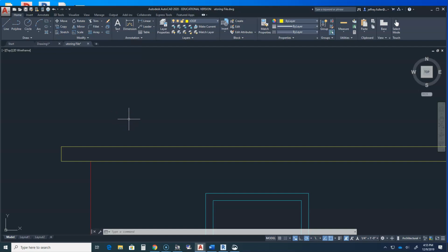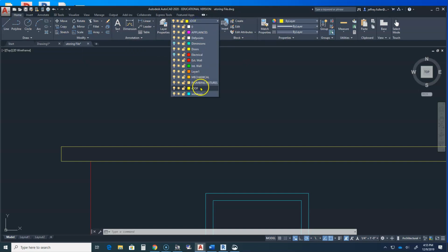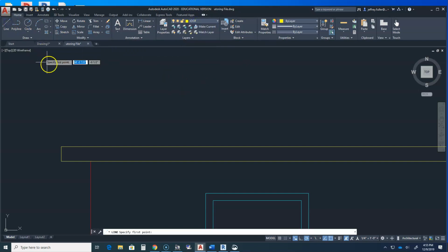over run. To establish this, we draw a couple of construction lines using the standard line tool. Go ahead and set your active layer to roof. Type line in dynamic input or select the line tool from the draw panel. Set the start point of the line at the top left corner of the fascia. Drag the line slightly to the right and type a value of 12 inches into the dynamic input. Now drag the line slightly upward and type a value of 6 inches in the dynamic input.